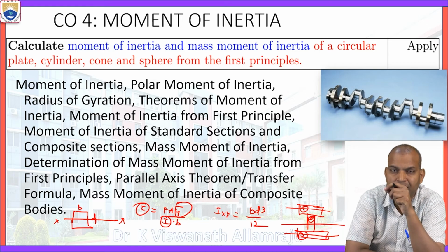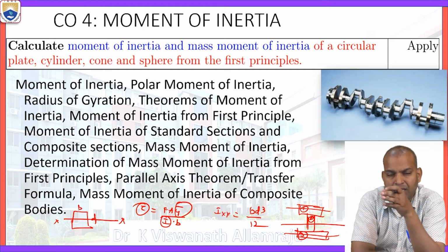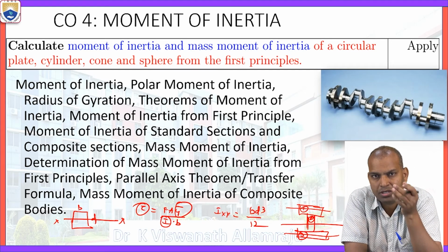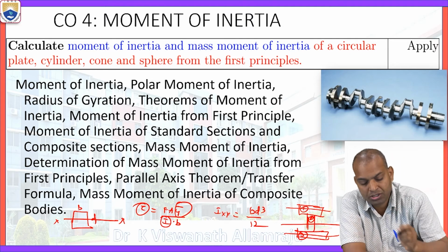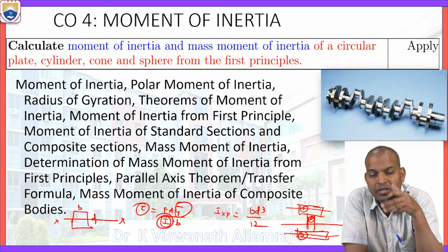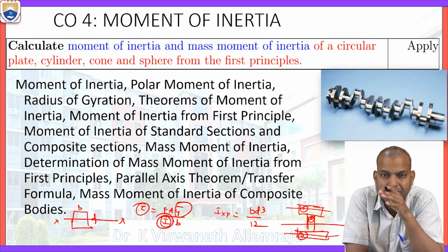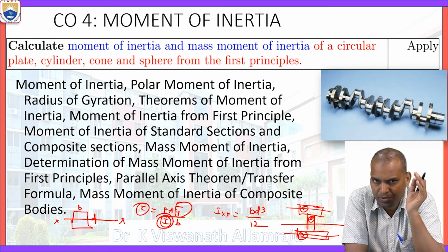That is module 3. Am I right? Yes, module 3. After applying the centroid concepts, we apply the parallel axis theorem, and by applying it you can find the moment of inertia. That moment of inertia value is highly useful to find the shear stress, the variation of the shear stress across the section of the beam. Okay. In the case of civil structures, there are various types of beams.